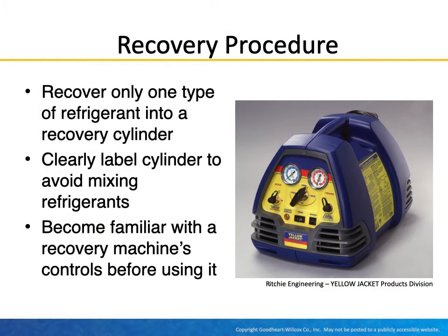Recovery procedure. Recover only one type of refrigerant into a recovery cylinder. Clearly label cylinder to avoid mixing refrigerants. Become familiar with a recovery machine's controls before using it.